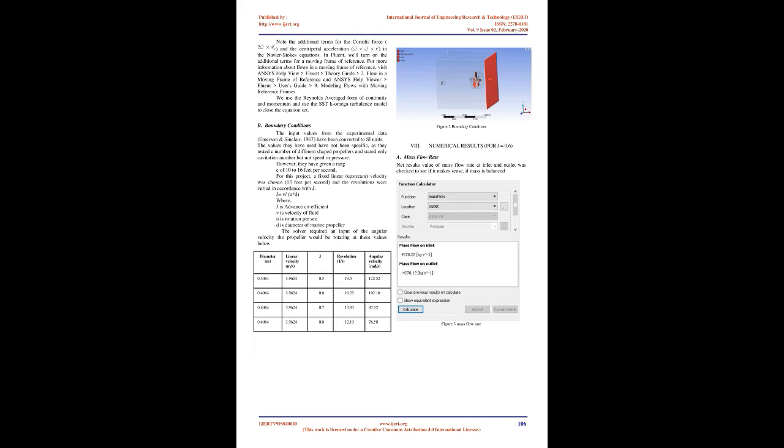6. Marine propeller specification. The coordinates of the blades were based on a 5-blade right-hand propeller, model KCD32, Emerson and Sinclair, 1967. The coordinates are set up as shown in figure 5.4.1. There are 7 sections, foils, at varying pitch and distance from the hub.